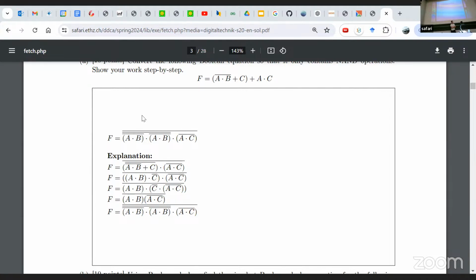And then the clock edge comes, and immediately after, a tiniest of hold time delay, the value is in there. At the same time, the new PC updates, and it's looking at the instruction, what do we get? And then it says, it's addi, and it's decoding, and says, what do I need? I need S0. S0 is already there. There's no problem with it.